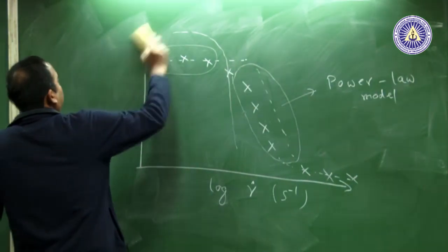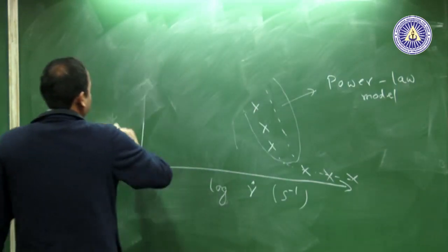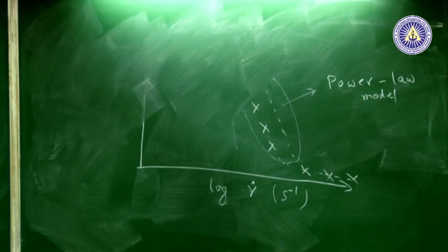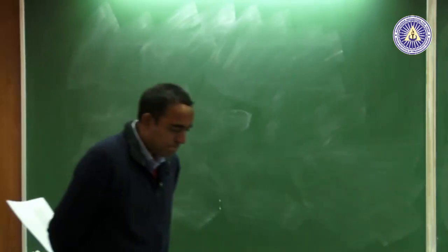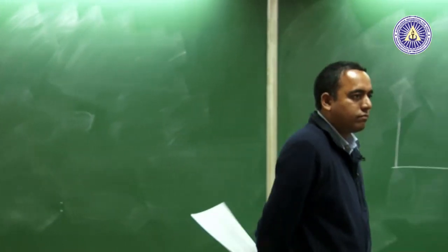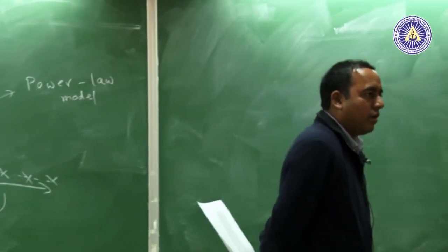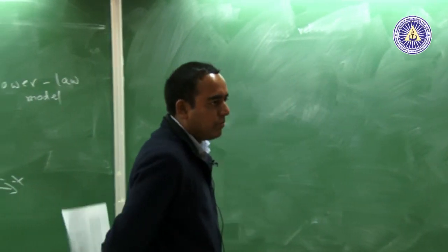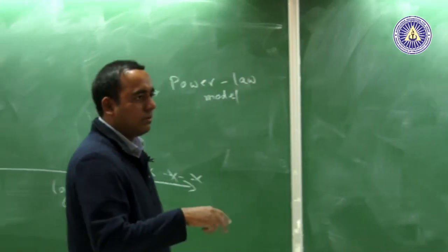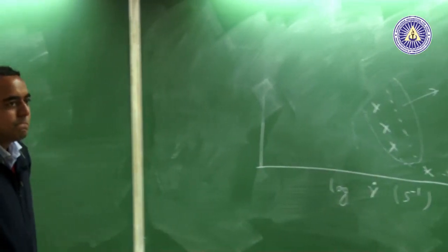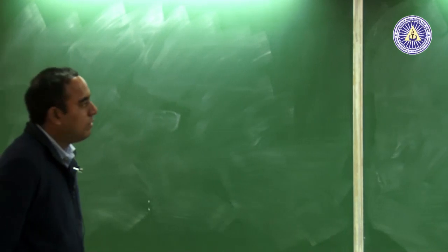So, with this background in mind, you measure tau 1 2 from the experiment, and we already have the gamma dot value, because we are imposing the gamma dot. And then you calculate eta as tau 1 2 divided by gamma dot.